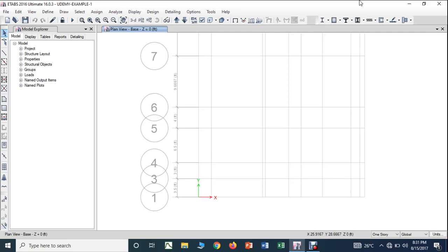The grade of concrete represents the characteristic strength of the given concrete when it is tested after curing for 28 days. That means when I say the grade of concrete is 20, then the average compressive strength, when you conduct the experiment on cubes after curing them for 28 days, should not come less than 20 Newton per mm square.